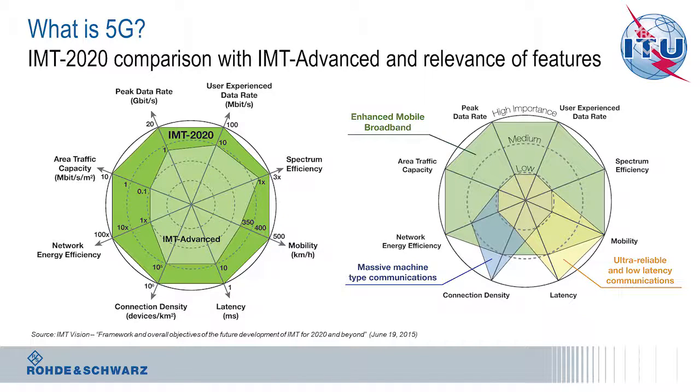These numbers show the theoretical possibilities of 5G in terms of peak data rates, for example. LTE Advanced is well capable going up to 1 gigabit per second and beyond, considering carrier aggregation of up to 5 component carriers with 20 megahertz of bandwidth, 256 QAM modulation, and 4x4 MIMO or 8x8 MIMO. Something we shall see maybe in 2016-2017 timeframe. IMT 2020 and therefore 5G needs to be better, of course.